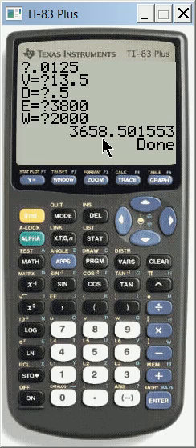Now, this is assuming no minor losses, and minor losses are going to be equal to some constant times the velocity head. Remember to chant the Bernoulli's equation. You chant the Bernoulli's equation, and that means what? It means you write y and you say the elevation in foot-pounds of elevation energy per pound of material.